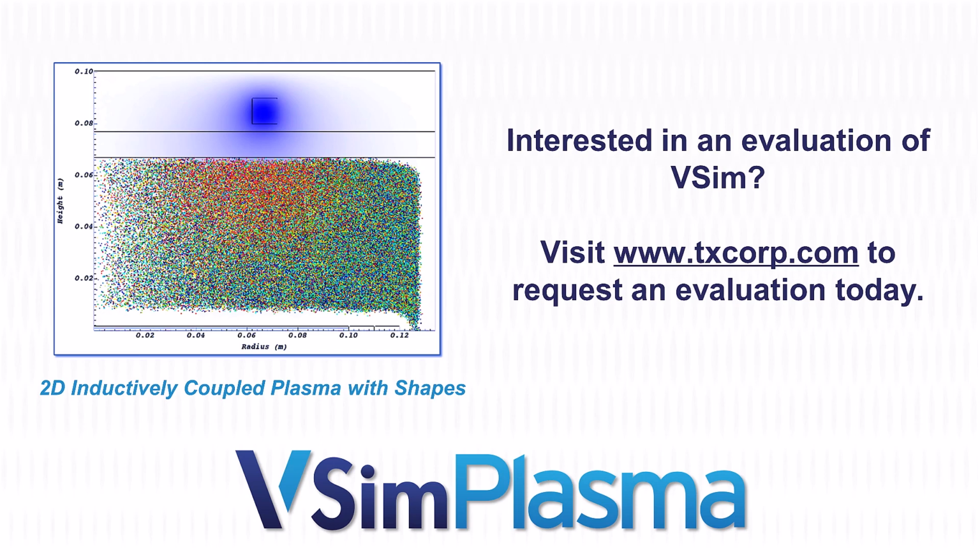The next question we have is, 100-volt bias means superimposing 100 volts onto the coil radiating 13.56 megahertz. I think that's just a confirmation. Is that correct? So the bias that we were putting in the simulation is actually a separate electrode that's underneath the wafer. So this would be for accelerating ions into the wafer for processing. However, you can also add a voltage on the antenna to model capacitive coupling from the antenna, which is important for resolving all the physics of inductively coupled plasmas.